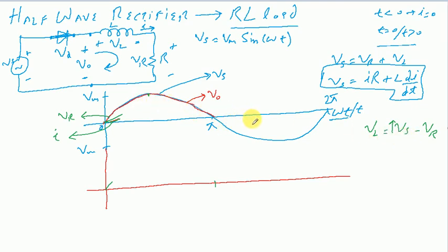So during that same interval, the current is also gradually rising, so the voltage across this load or this resistance is also rising. So what happens is that during this time interval the inductor is also energizing and the voltage across the inductor is also gradually rising. So there is a brief time during which all of these voltages have waveforms or slopes of something like this.